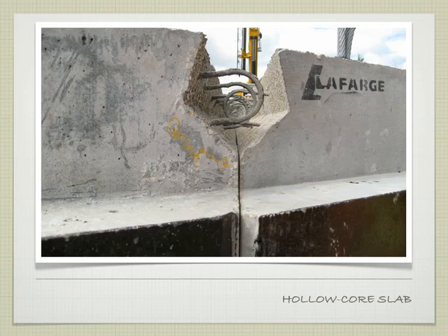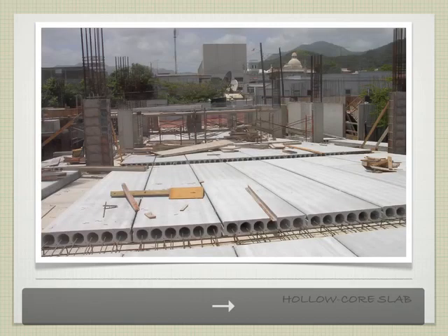At the edge, in this particular example, we have this notch that's been left out, and we have this series of rebar pieces. This one coming from here, there's another one from this side, but then we have an opposite interlocking piece coming from this piece. We will then pour the topping on top of this, and it will fill this cavity between the two and lock the two pieces of rebar together, making it one solid slab, ultimately. Does that make sense? So that's how we tie these things together.